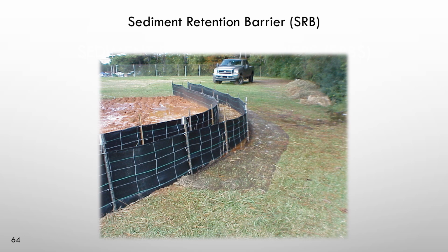But again, clays are going to go right through the silt fence. If we have our polymer treated media in between those 2 rows, it's going to flocculate out those clays, it's going to attach to that straw or that mulch, and then we have clear water moving through the back end. So this is a really great option if we have turbid sheet flow or as kind of a last line